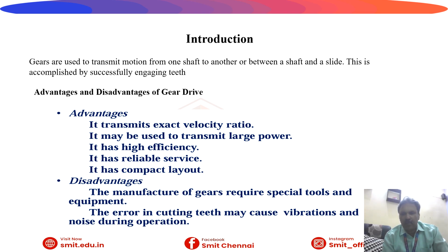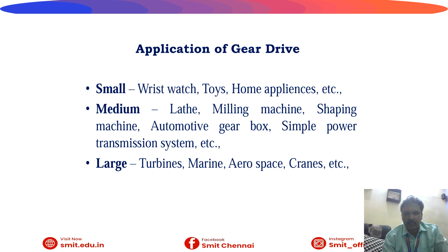It has a compact layout. Disadvantages of gear drives: manufacture of gears requires special tools and equipment. Error in cutting teeth may cause vibrations and noise during operation. So these are the major limitations. Manufacturing requires very special tools, and errors in cutting teeth may cause vibrations and noise. Now the applications, all are aware of that.